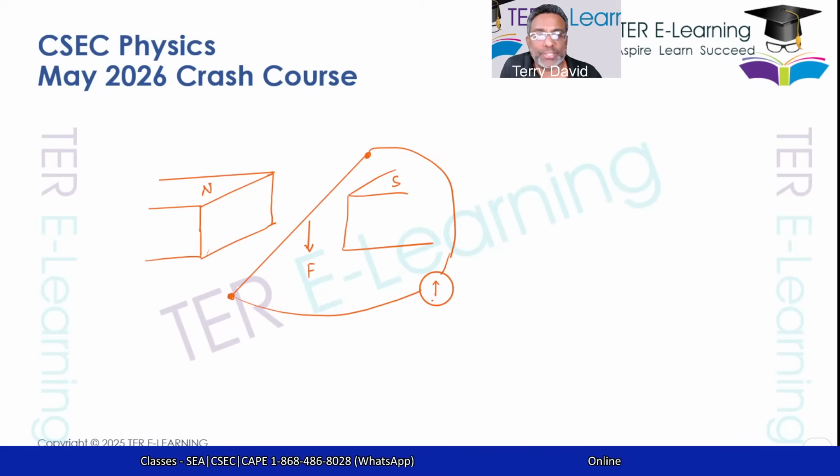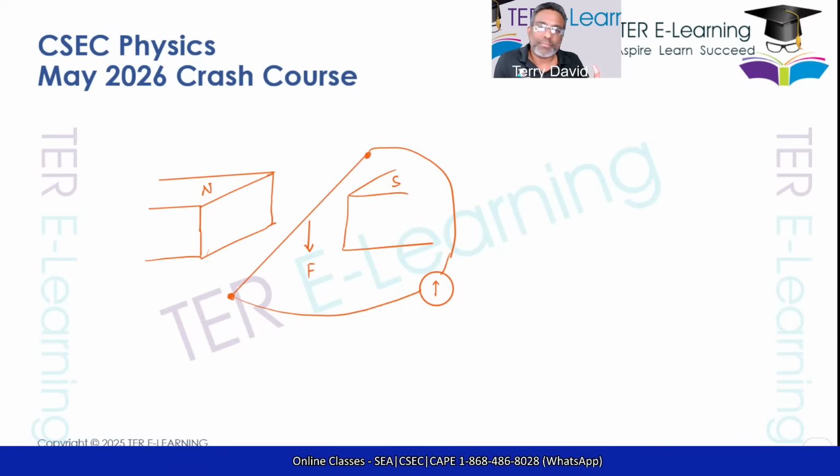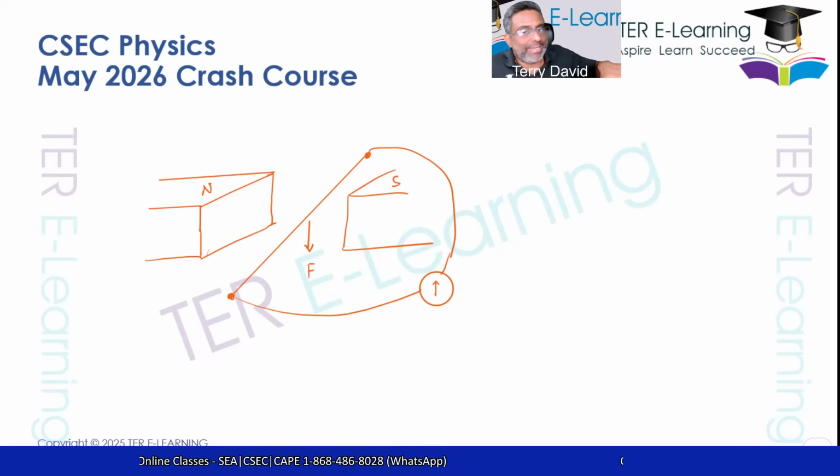So here's how we're going to do this. This is where students have trouble. First of all, I'm using my right hand. I'm not sure how it's going to look on your end. This is my right hand here. The first thing I normally do, I take my pointing finger, my index finger, and point it in the direction of the magnetic field, so that's north to south. Then your thumb has to point in the direction of the force, which in this case is downwards. So that's going to be like this.